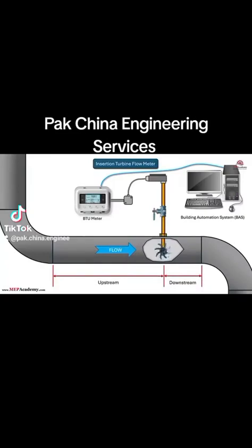There will be a low pressure drop caused by the turbine wheel, and since they have moving parts, the maintenance will be greater in addition to the time between recalibrations.